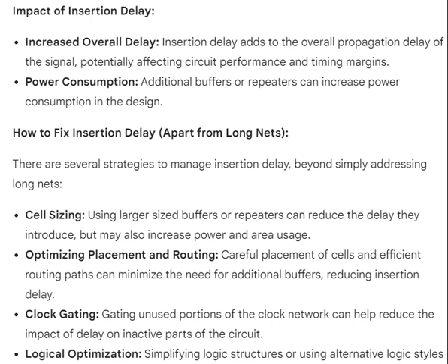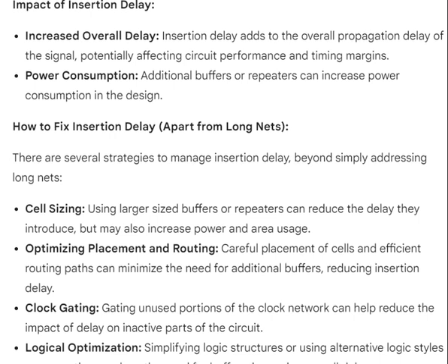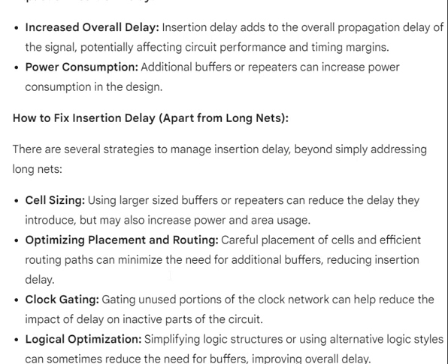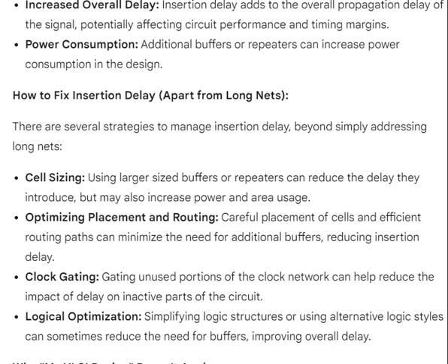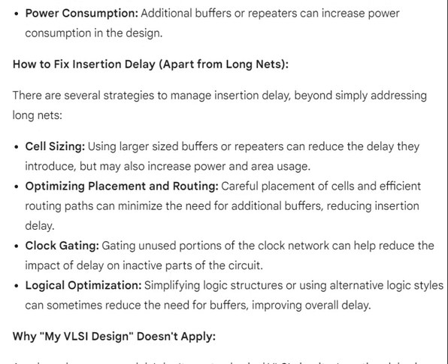Elements are inserted, which strengthens the impact of insertion delay. Increased overall delay. Insertion delay adds to the overall propagation delay of the signal, potentially affecting circuit performance and timing margins. Power consumption. Additional buffers or repeaters can increase power consumption in the design. How to fix insertion delay, apart from long nets?